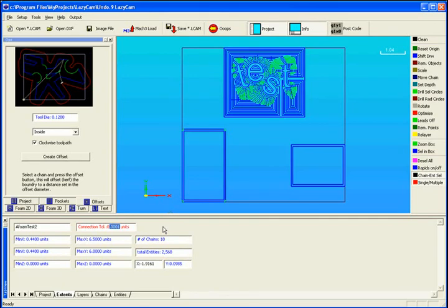With some drawings, your lines may not be touching perfectly, so you may have to increase that number to give the program a set tolerance to use when joining entities into a chain. If you leave it at too high a number, you may find some operations like pocketing and offsetting get a bit screwy. By setting it back to 0.0001, suddenly you'll find it does the proper offset or pocket. It's not always the problem when you have a problem, but it can be.